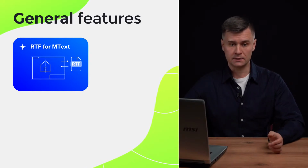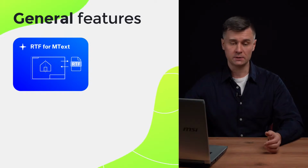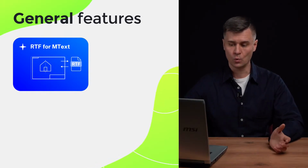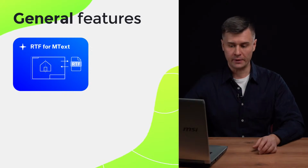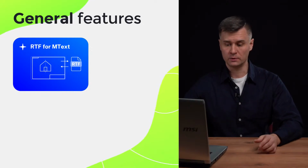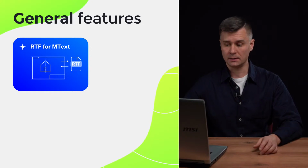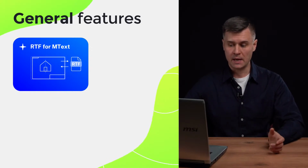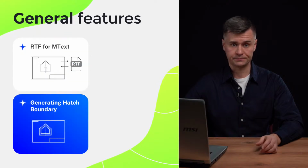To enhance our existing text processing capabilities, recently we introduced a two-way conversion between MText entities and RTF strings. So in addition to the set contents RTF method, we implemented a contents RTF method that returns the MText object as an RTF encoded string.